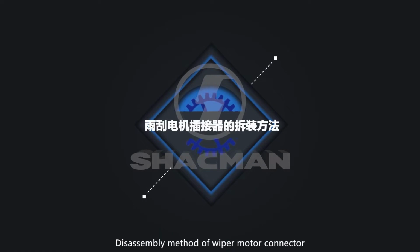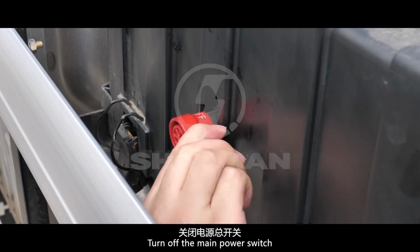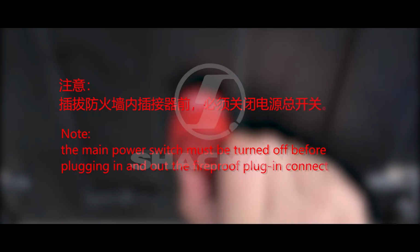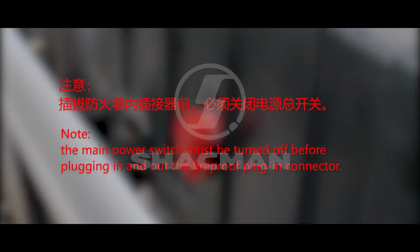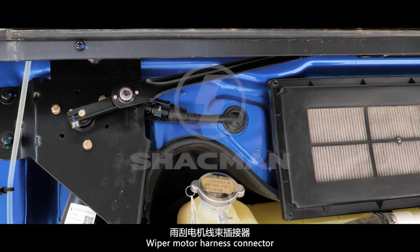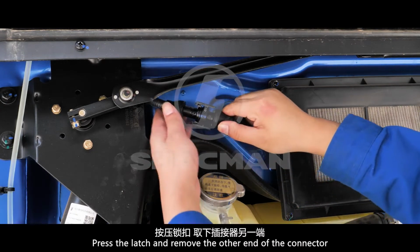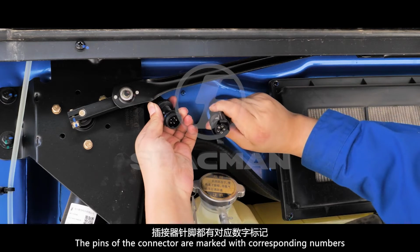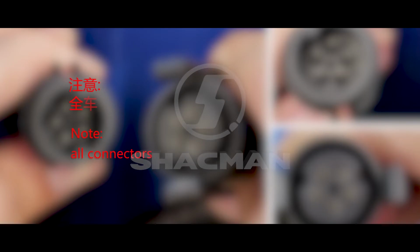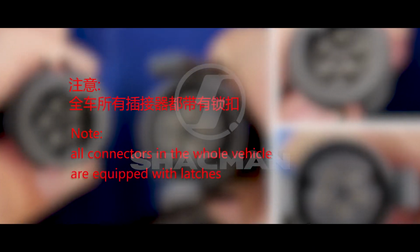Disassembly method of wiper motor connector. Turn off the main power switch. Note: the main power switch must be turned off before plugging in and out the fireproof plug-in connector. Wiper motor harness connector. Press the latch and remove the other end of the connector. The pins of the connector are marked with corresponding numbers. Note: all connectors in the whole vehicle are equipped with latches.